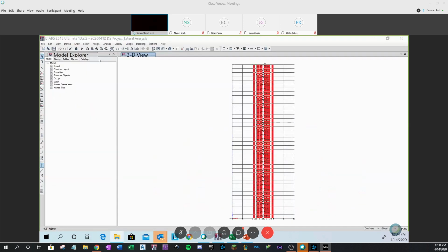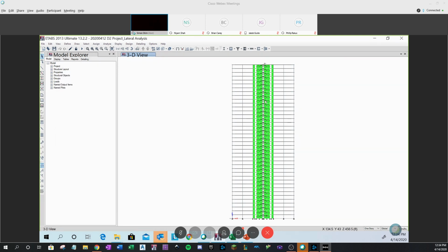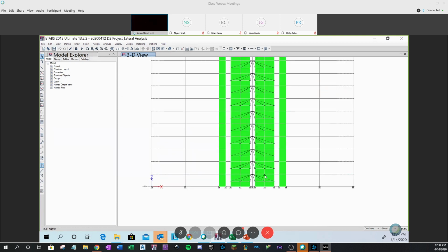So once you set up, I think now you did. We haven't done it yet. Even though section properties are turned on, you see that everything is the same size, because obviously you just copied all the way up. Now, one thing I have to explain here is the diaphragm. Somehow you may see, while you're copying, that you meshed the wall so there is an internal mesh here. That has some issues. If you do this, you have to do it carefully.